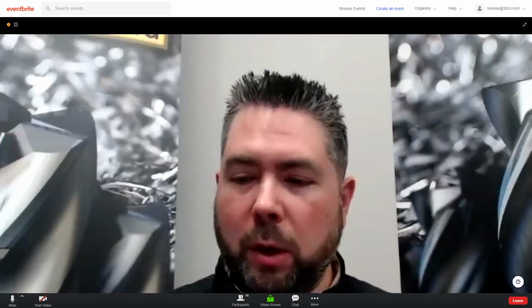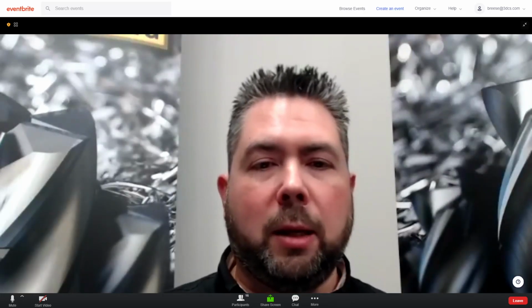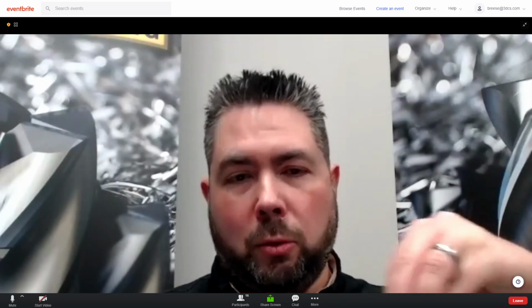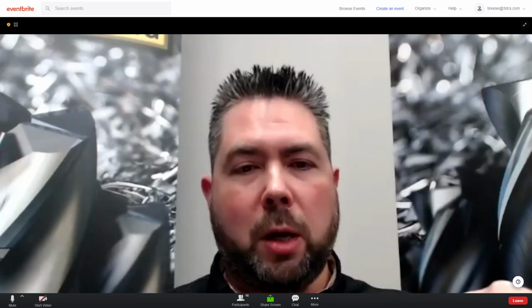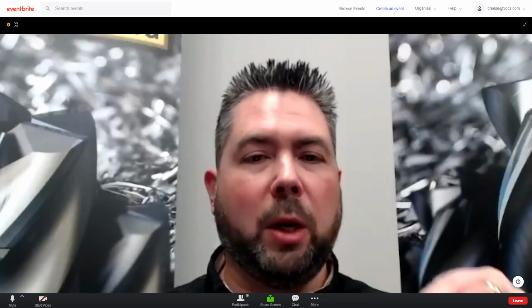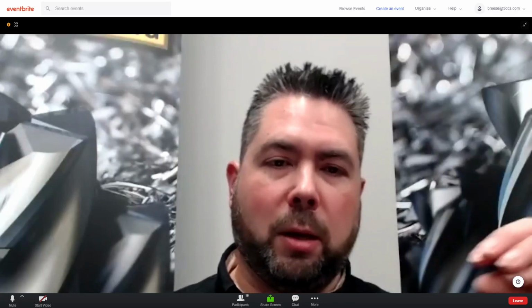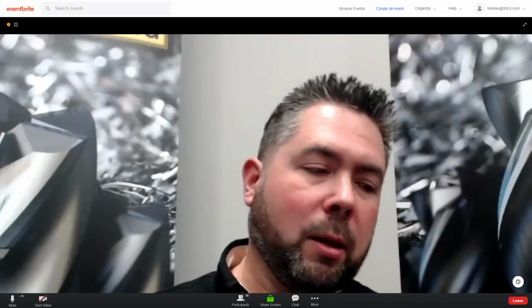If I want to be really productive and I've got a lot of pockets to make, I might take something like that 4-flute TE tool I showed, go in and blow out the center of it with a traditional cut, and then come in with a dynamic tool and finish the rest of it. That TE tool can slot at 40 or can ramp at 45 degrees.